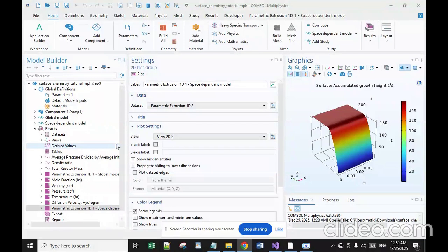Ozone glasses have excellent conformality but tend to be hygroscopic, that is, they absorb water from the air due to the incorporation of silanol in the glass. Infrared spectroscopy and mechanical strain as a function of temperature are valuable diagnostic tools for diagnosing such problems.